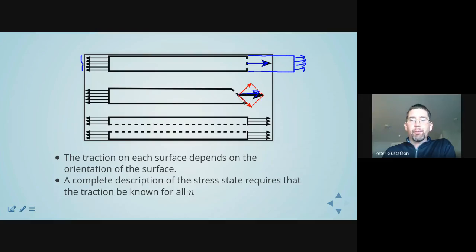Whereas here on this 45-degree plane, this reaction force vector, this integrated internal load vector, has to have components, one of them being normal, I'm highlighting now, and one of them being in a shear direction relative to that surface, which I've highlighted. So the magnitude of the normal component has changed from here to here. The reaction vector overall has not changed, but the component of that vector that's associated with the normal direction to our internal surface has changed in magnitude, as has the shear vector.